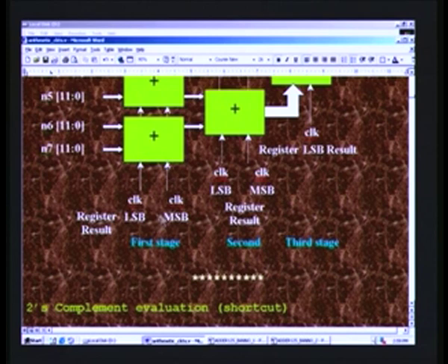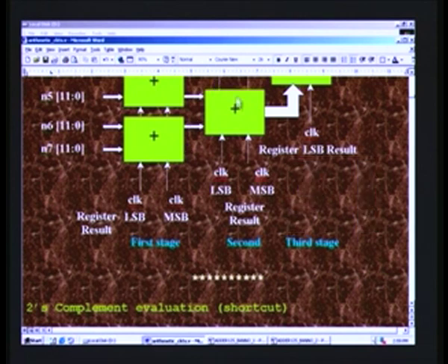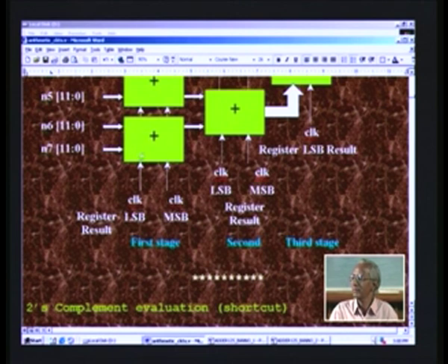And this is how we pipeline. So you see that every function is divided, and LSB, MSB are basically performing that add operation, and in this case all of them are add, so you won't know the functionality partitioning, although functionality partitioning is also implied here. So LSB, MSB is treated inside, whereas the actual functioning we can treat it as this is one adder, this is another adder, and so on. So that is how different functionality is also partitioned. Therefore, this particular design has partitioning of not only data width but also the functionality.